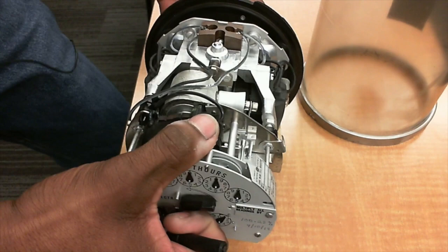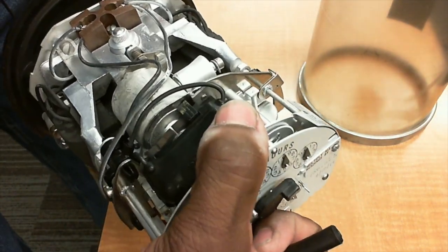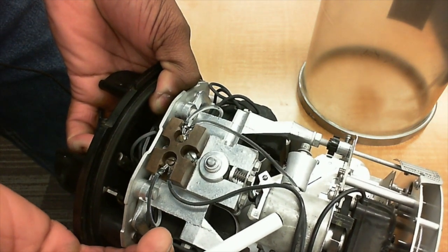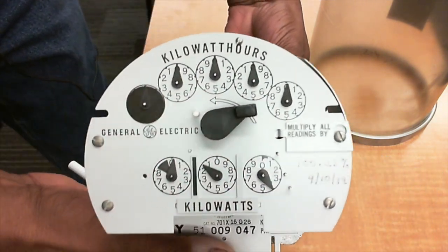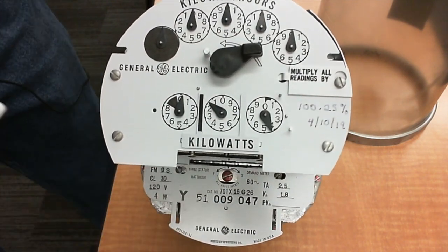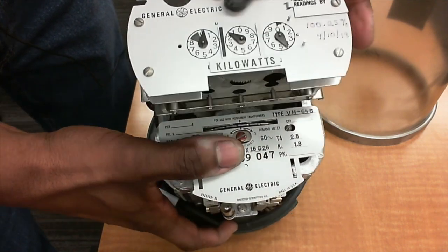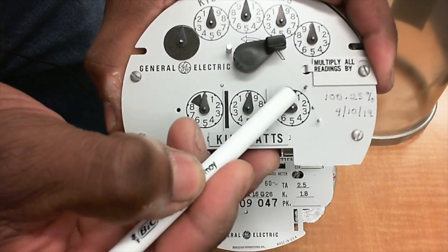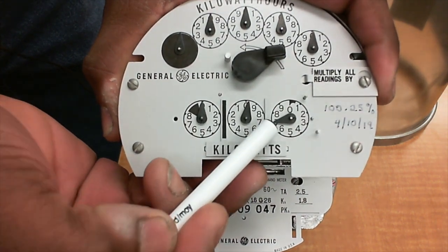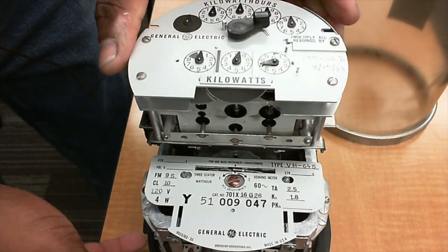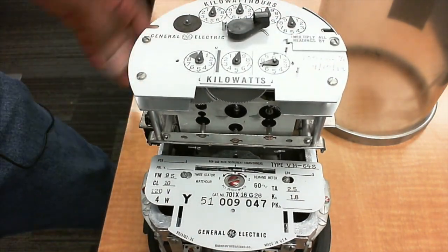The second thing is, here's actually the demand motor that Chris had mentioned. That motor there is the main culprit here that has the issues. That motor there operates these little dials down here. And of course you can see what I was saying, if you reset this, you see that this dial doesn't go all the way to 0, it's actually going past. So that's a quick indicator that you've got some problems.